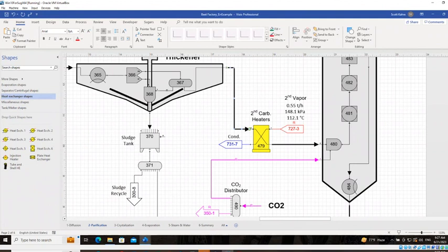Okay, so this is getting into a little bit of a different subject matter, but just real quickly, I'll mention that if you have parallel steam in your evaporator train, you'll need to set one of those effects up to operate independently, because there's an extra degree of freedom created when you put parallel effects in an evaporator train.